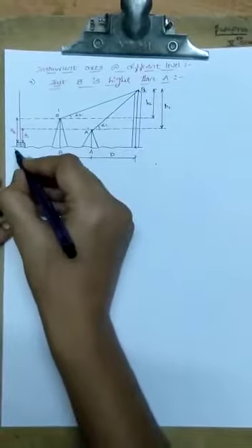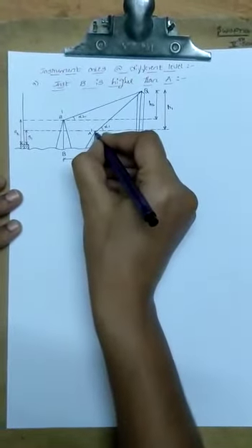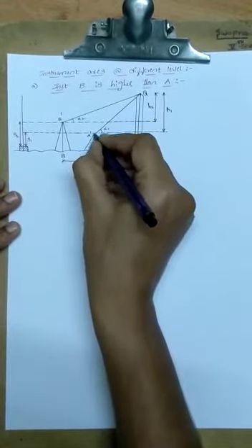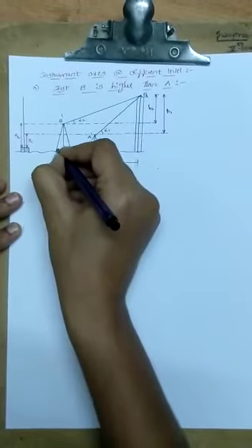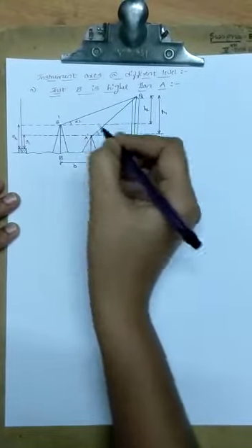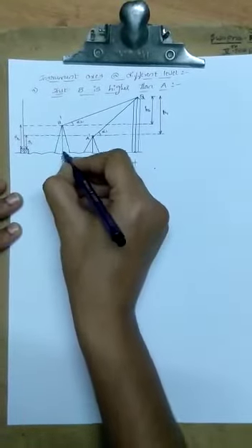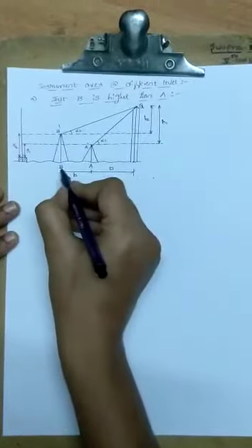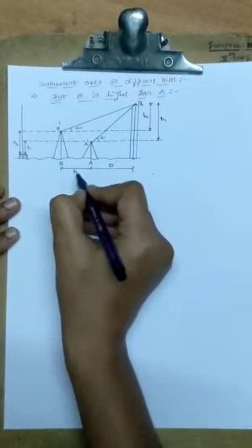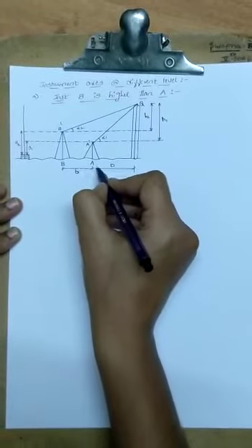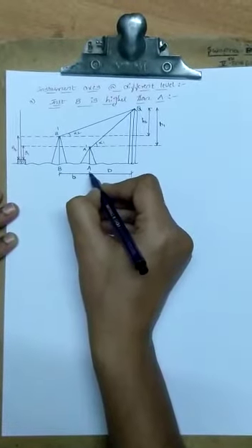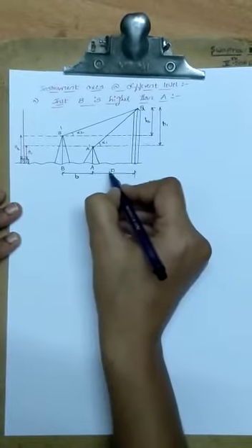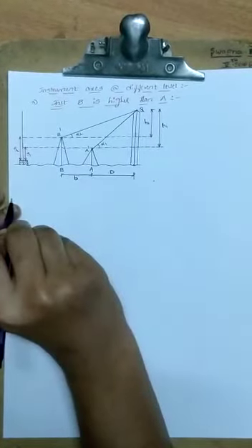Okay. See, this is the figure. This is the ground point. Okay. This will be the instrument at the A station, and this will be the instrument at the B station. The instrument at the B station is higher compared to the instrument at the A station. Distance between the instrument A and B is denoted by B, and the distance from the instrument station, that is the first station, to that elevated object, is denoted by D value.